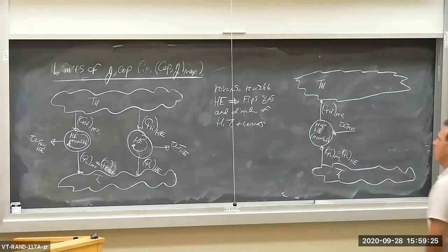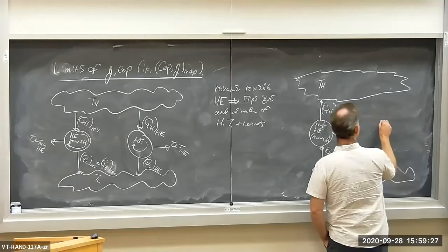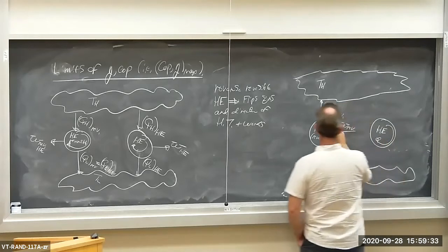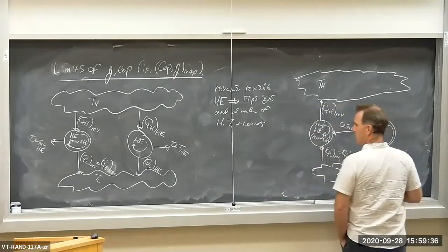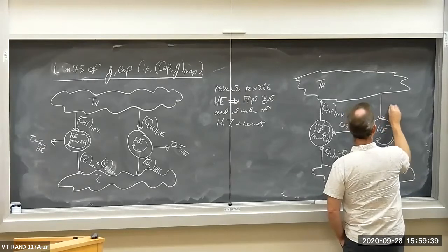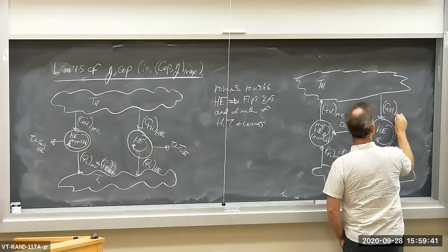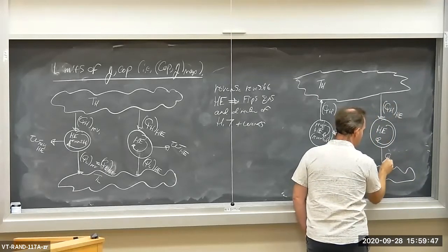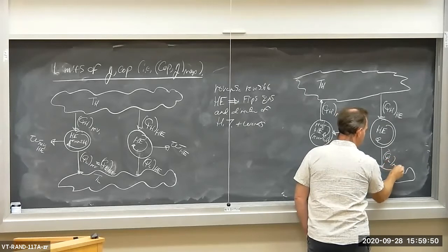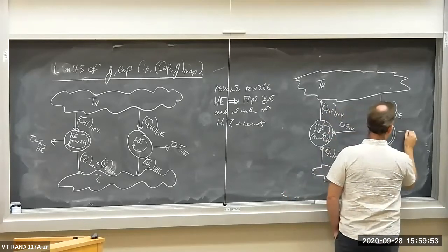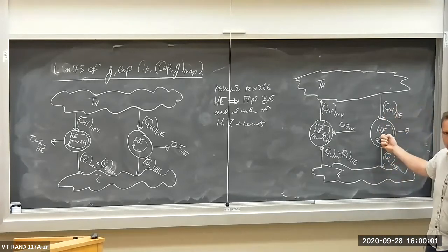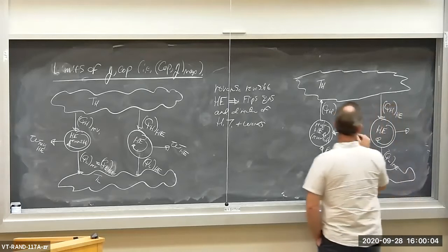Let me put in my regular heat engine, which is to the right. So here's my regular heat engine. It's working in a cycle. These are all working in a cycle. So this guy received QH, heat transfer from the high temperature reservoir, rejected some heat QL to the low temperature reservoir, producing a certain amount of work. Now here's the key. I'm going to take some of the work produced by the heat engine to drive the reversible heat engine.